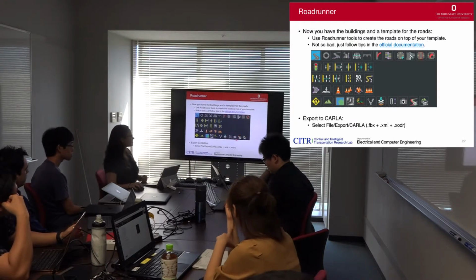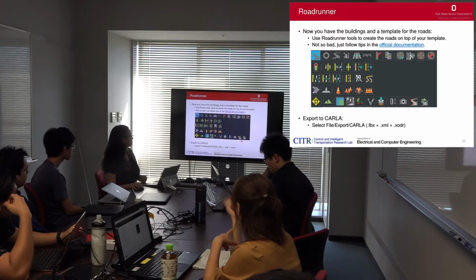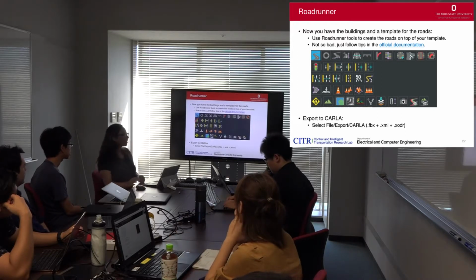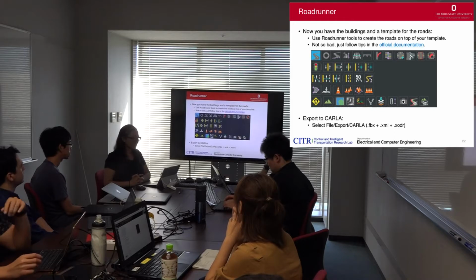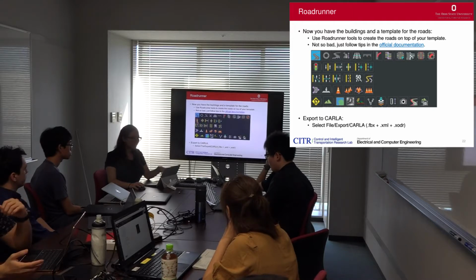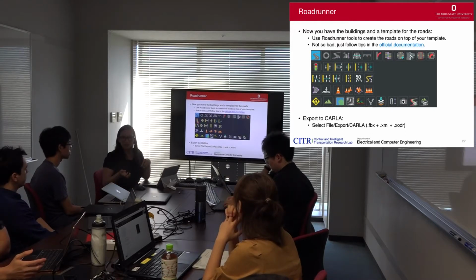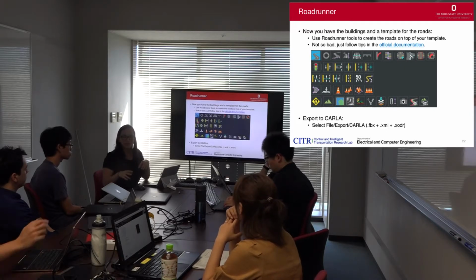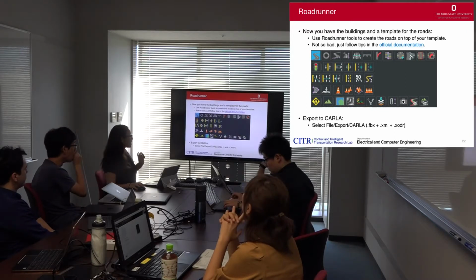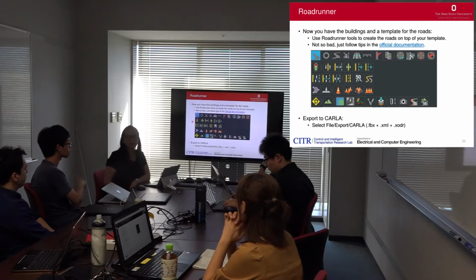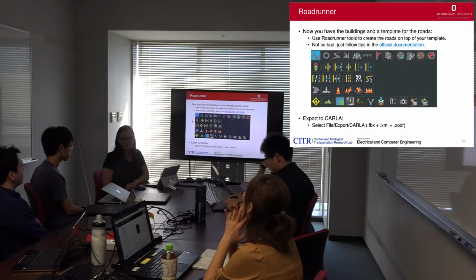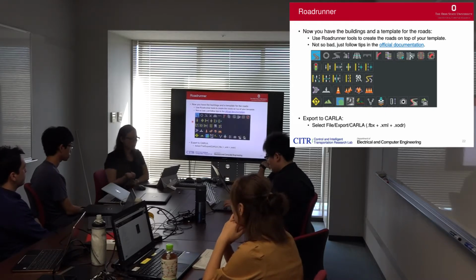Okay. And here there are traffic lights, so why can the exported OpenDRIVE file not recognize that? I don't know why. Is it that this tool doesn't support traffic lights, or is it not supported in this file format? The traffic light logic is included here, but it is not exported to Carla. You have to regenerate it in Carla, something like that. This doesn't work very well yet. They say it will in the future, but so far it doesn't work. So if you place the traffic lights, it won't necessarily work when you export it to Carla. The signals are not cooked.